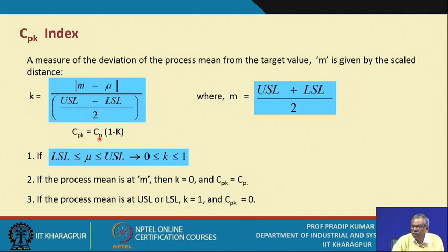That means, if Cp is 1.5 or say 1.67, Cpk is also 1.67. So, that condition you must be able to reach. And what are these conditions we are referring to? This condition refers to the centering of the process. That means, the first exercise you try to do is reduce the distance between m and mu. Is it okay?